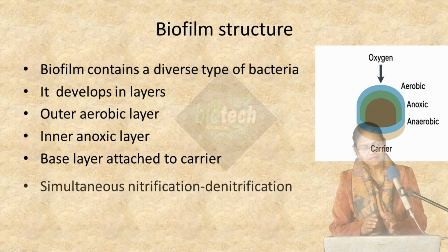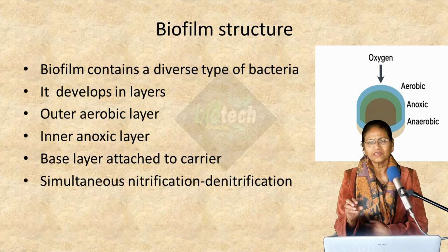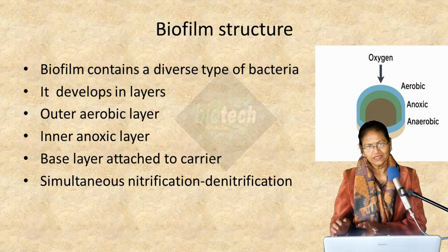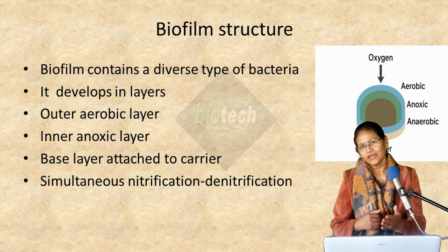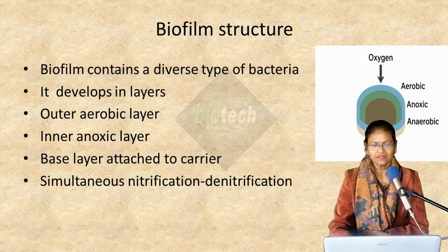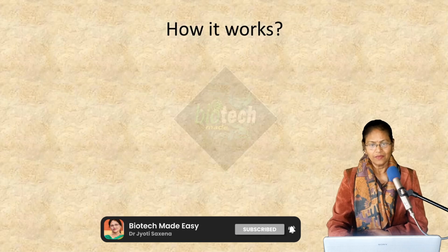Here simultaneous nitrification and denitrification, although the denitrification is very, very low, but still nitrification and denitrification both can go on together because of the presence of aerobic as well as anaerobic bacteria. Let's see how this works, MBBR.